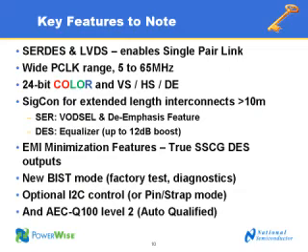Signal conditioning for extended length interconnects going greater than 10 meters. And that's on the serializer with the VOD cell and the de-emphasis, and also on the deserializer with the equalizer up to 12 dB boost. And EMI minimization features, so the true spread spectrum clock generation on the DES outputs, which is the SSCG outputs.